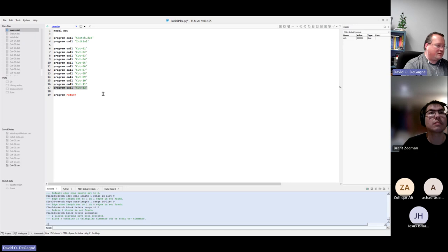It may not be a factor of safety of 1.25, but then you run the factor of safety analysis. If it comes out at 1.1, then the backfill strength has to go up. And then you know that it will be stable, so you can just jump right into the factor of safety analysis and see what you get. Okay.